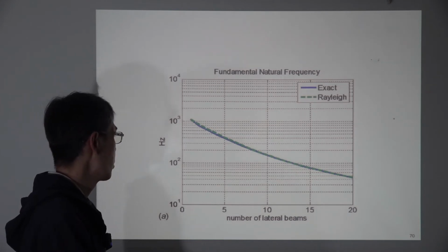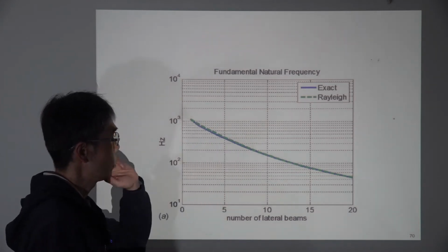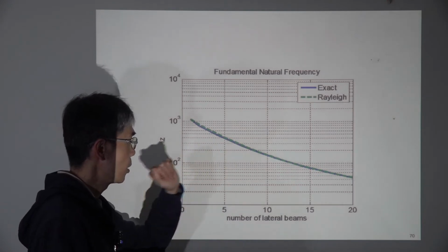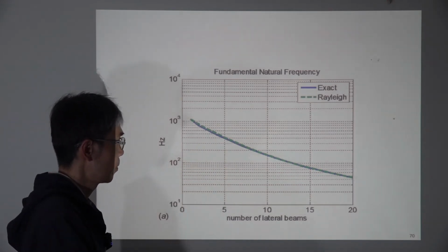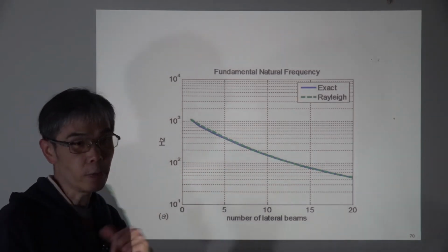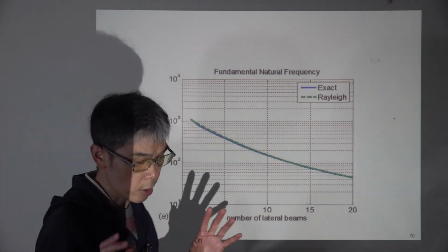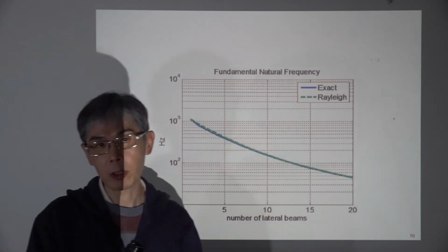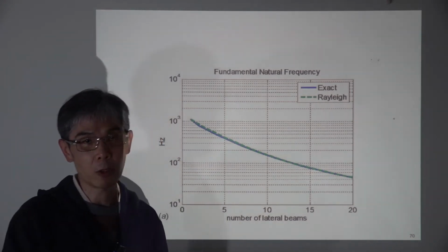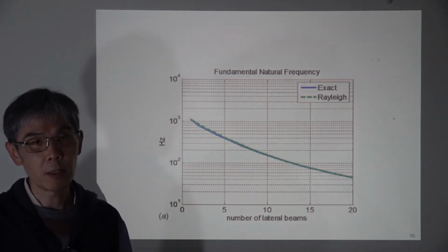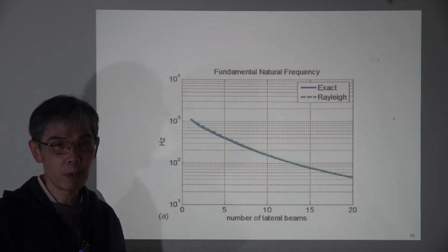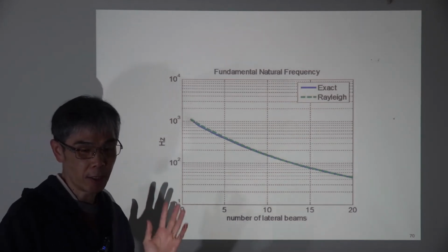For the lowest mode, the Rayleigh method is almost the same as the exact solution. We show that the Rayleigh method is quite efficient. Using the static deflection solution as a trial function is quite convenient and accurate in this case.